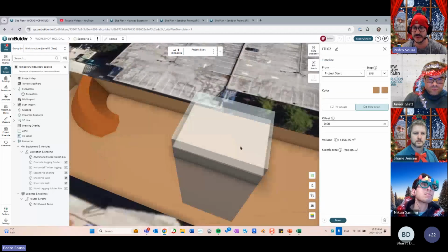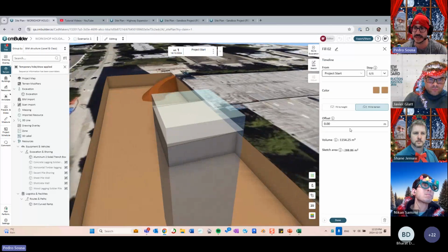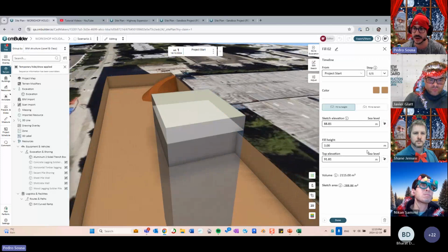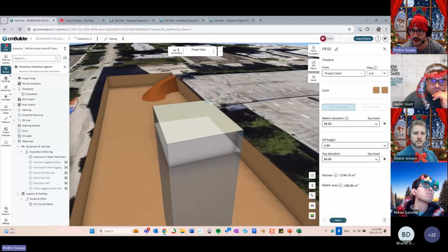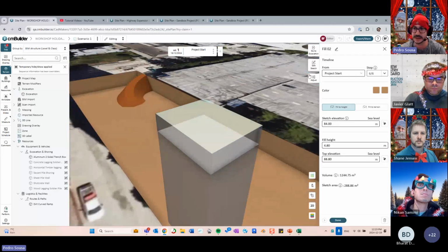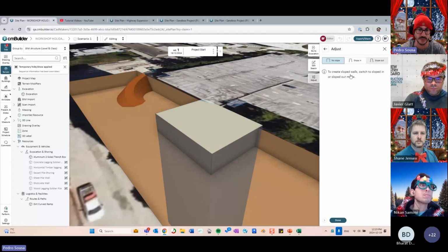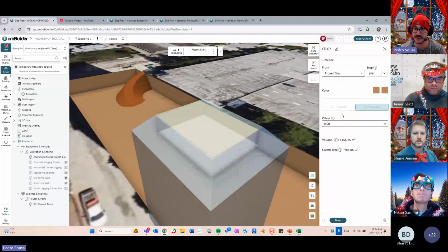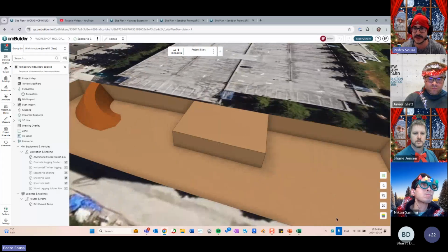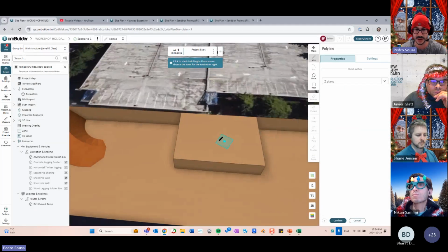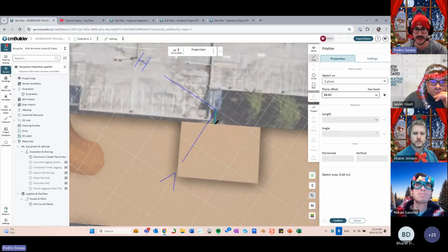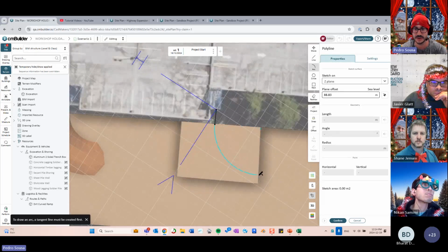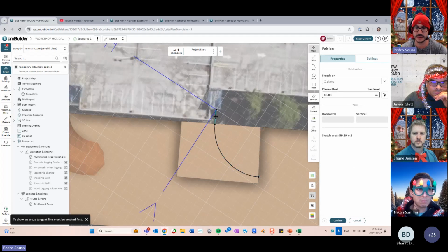So if I create a fill over here, that brings me back to my terrain, or fill to height, where I want the height of this fill to be something like that, to have maybe a slope on the outside or things like that. You can do that as well, but let me just do it with the fill to height. And then from here, I can go and create a trench that would be a curve, right? So I'm going to create that trench first, and then I'm going to do a curve, and then delete this one.